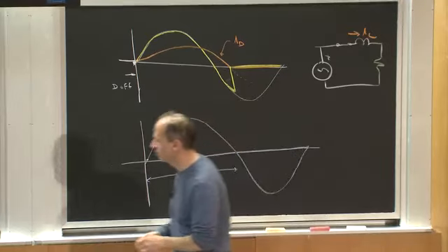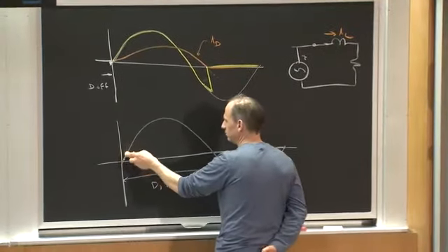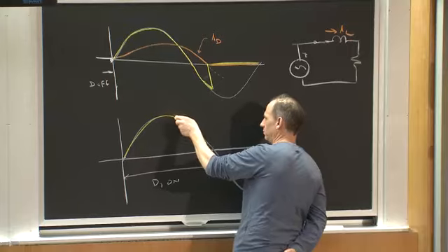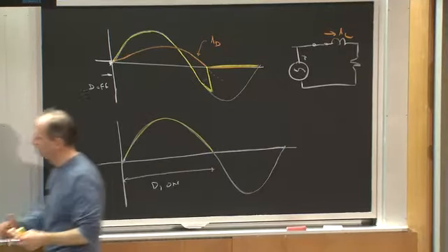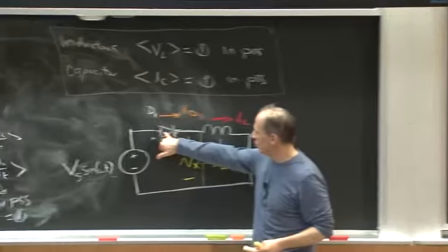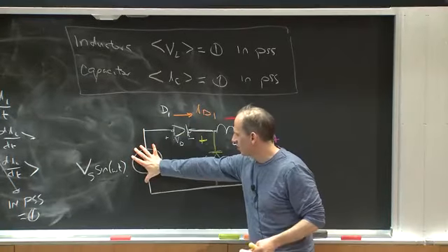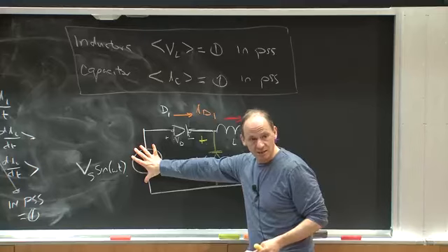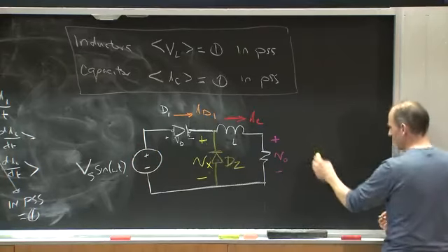Right? And I'm going to get a voltage Vx that looks like this. It's going to follow this. Now, what happens when Vx goes negative? If I assume that D1 is on and Vs sine omega t becomes negative, and D2 is off, I'd have this configuration.